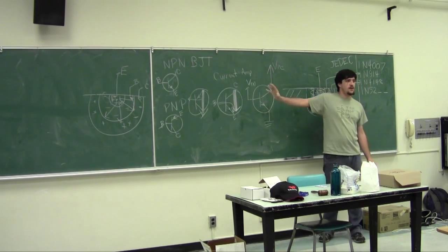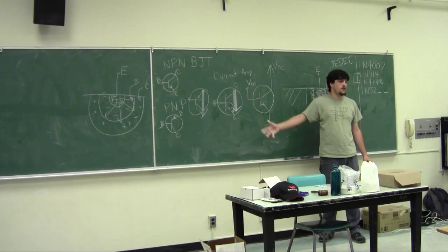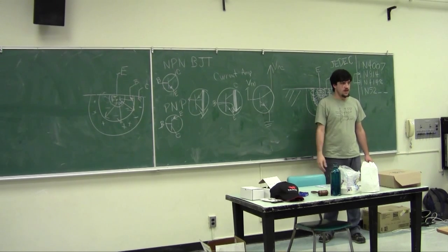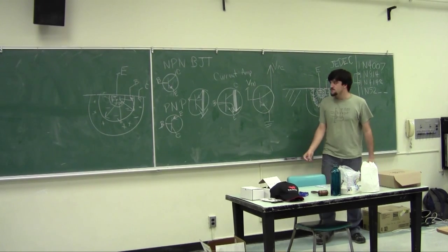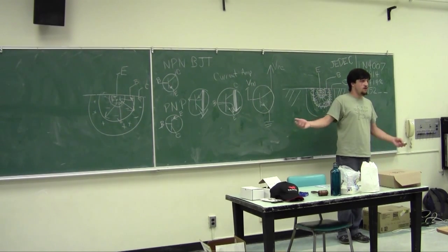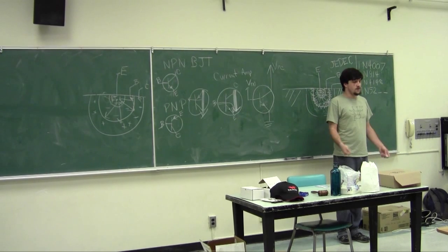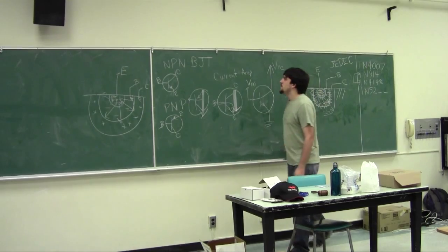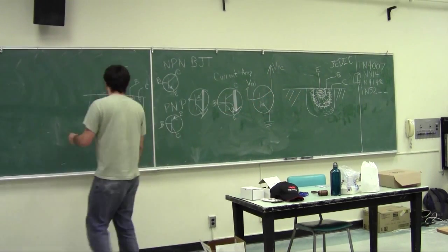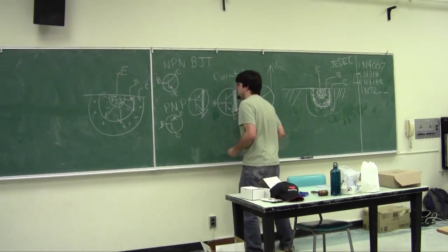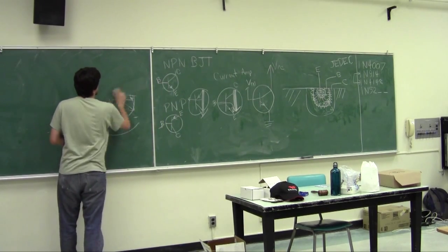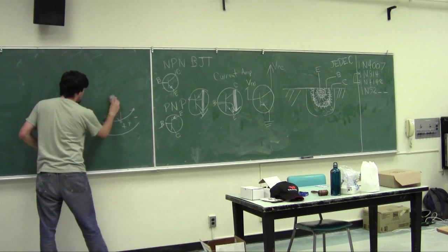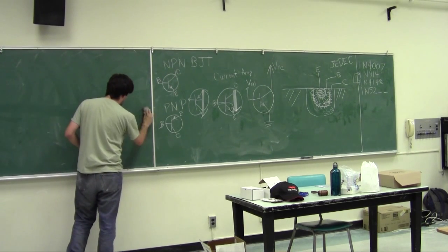Now you've thought, hey, this amplifier thing is kind of cool. I actually want to use an amplifier in one of our circuits. So if you go to a catalog and ask for a transistor, they're going to look at you like you're crazy because you need to specify which transistor you want. Like I explained for the diodes, there is a naming convention for them where they will often start with 2N. And this 2N is a naming convention from the US.